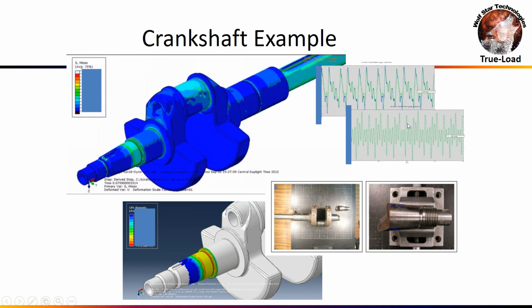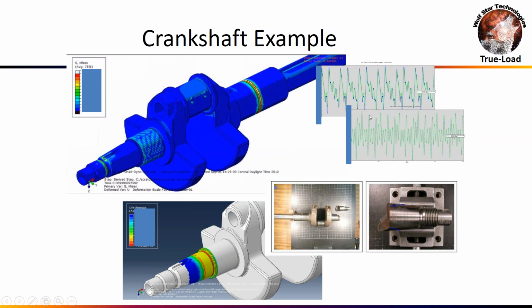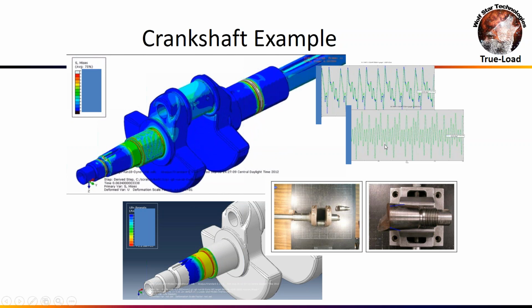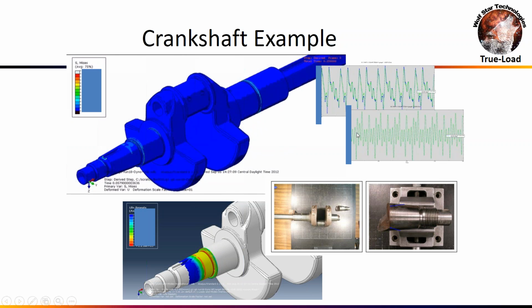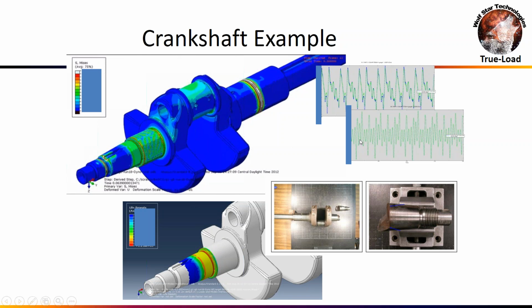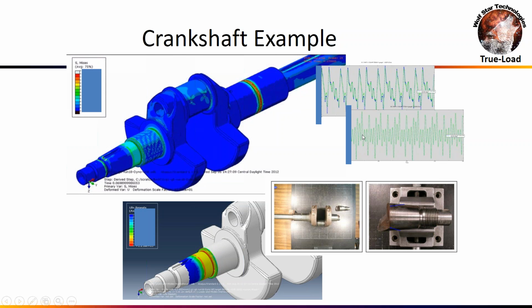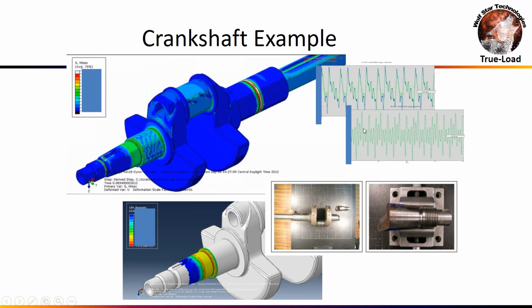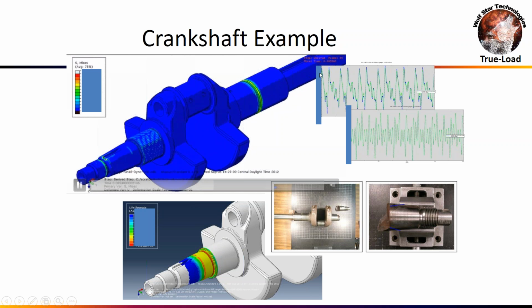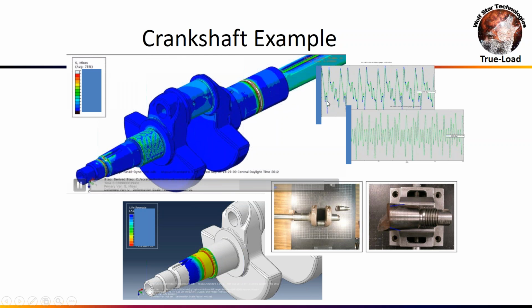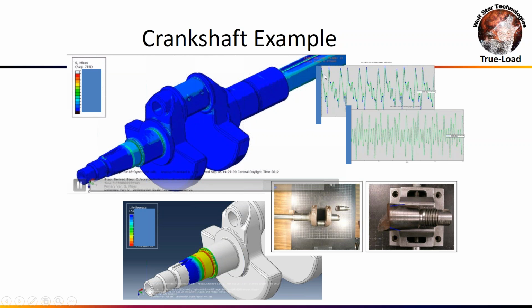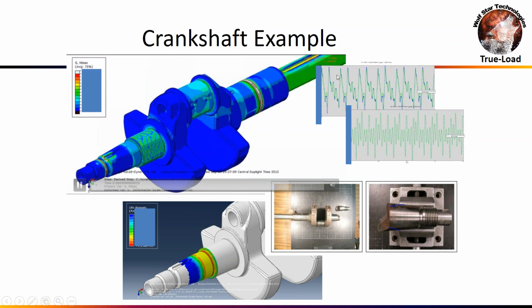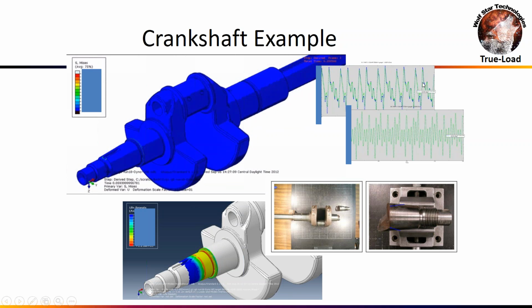And then what I'm showing you here are what I call my best and my worst plots. So the best of the best, the worst of the worst. The bottom plot here shows the green as the measured strain and the blue as the simulated strain, and they are line on line, less than 0.01% error. And even my worst strain gauge on this part had about 1% strain error.